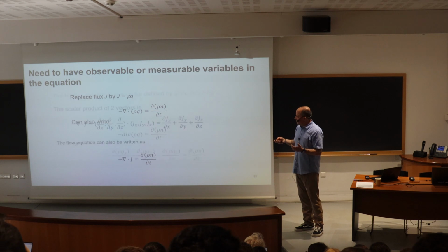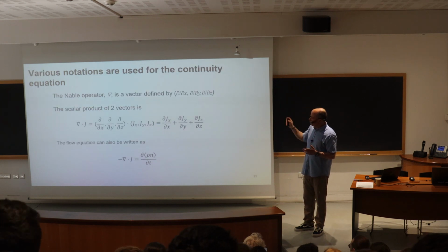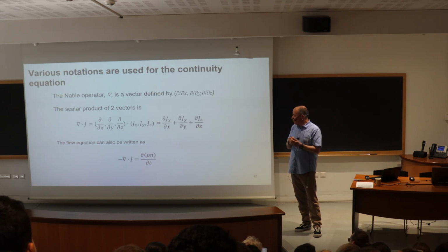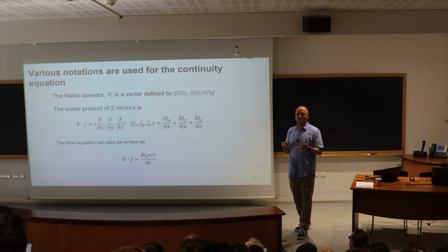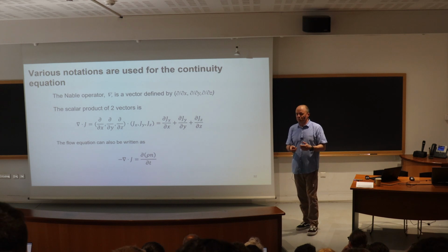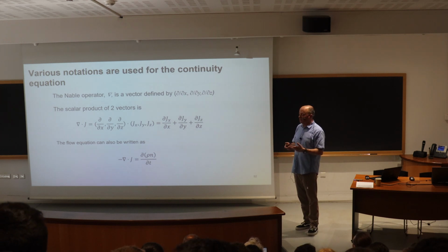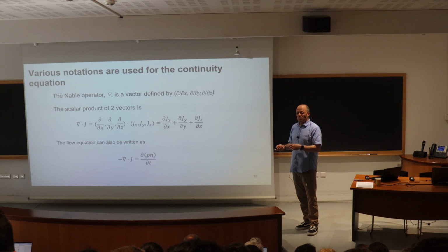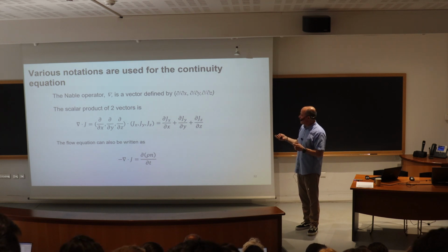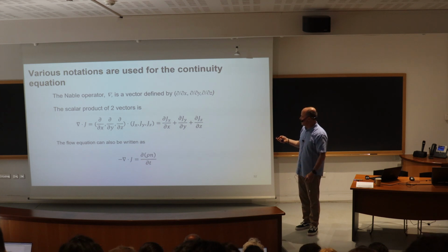So if I go back to the equation, no matter what notation, except for porosity and density on the flow side, it doesn't really contain quantities that we can easily measure. We don't really measure the Darcy flux. We don't really measure the mass flux. So we have to simplify to get measurable quantities in our equation. And what do we measure in hydrogeology? Hydraulic head. So that's something that we should have in our equation, because that's the energy of water.